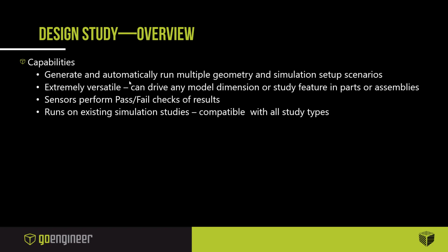To give a brief overview of design studies, its capabilities are as follows. It has the ability to generate and automatically run multiple scenarios of our model geometry, our feature size, or variations in our simulation setup, maybe different loads, different fixtures, different initial displacements. It has the ability to automatically generate these scenarios and run them for us. This makes it extremely versatile. If it is a user-based input in your SOLIDWORKS model or simulation study, likely it is something that the design study can actually drive and use and vary.